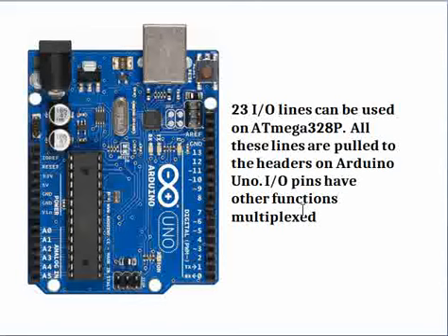lines, because these IO lines are multiplexed with several other functionalities. For example, we have talked about analog, I2C, SPI, PWM, right? And then UART, that's the preliminary thing. All these functionalities are multiplexed with the GPIO pins. That means a specific pin supports either GPIO or the other function.